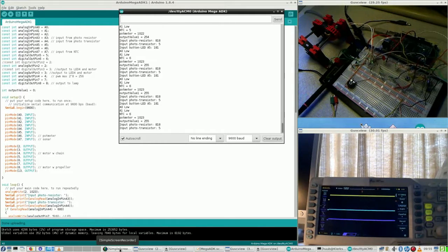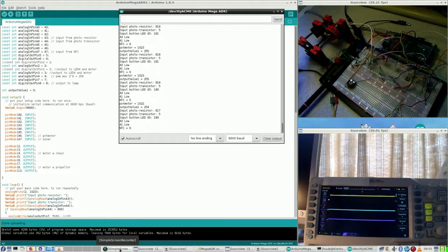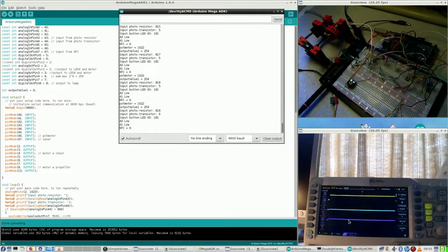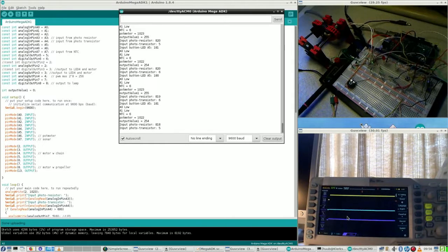Right, now that this is not working is explainable. If we look at this signal, which is this probe, then the voltage is quite low. Assuming that 5 volts is this level, from here to here is 5 volts, and this is about maybe 1 volt, and that is way too little. This is 5 volts, and no matter the pulse modulation, it needs voltage.